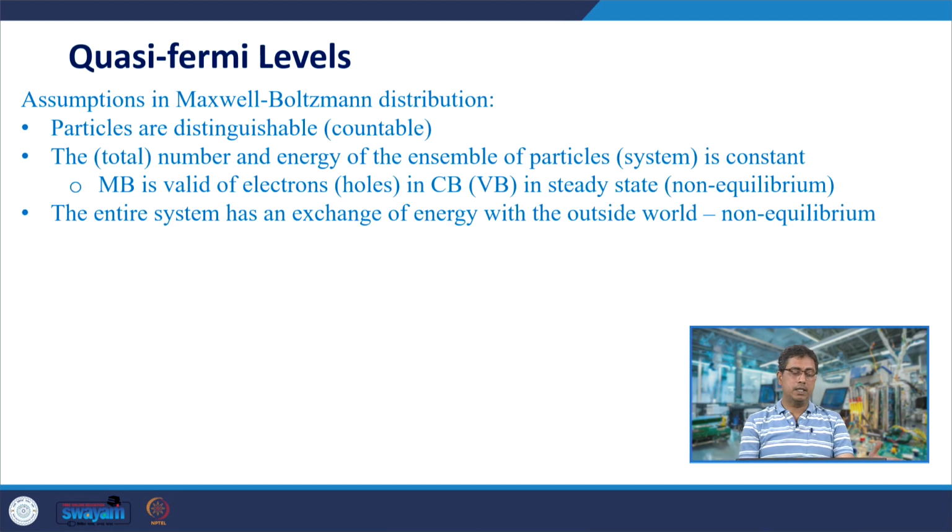So, what is this idea of quasi-Fermi level? We use quasi-Fermi levels to estimate the carrier concentrations, electron and hole concentration, in different parts of the device, in non-equilibrium condition, when the device is not in equilibrium condition. And as we had discussed, in a MOSFET, if the drain to source voltage and body voltage are 0 and you